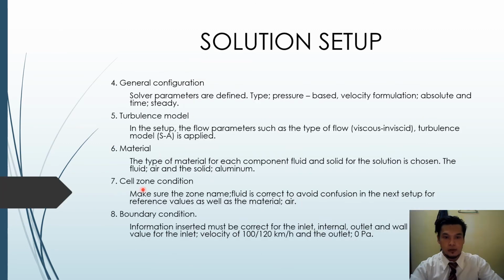For the cell zone condition setup, make sure the zone name is correct, which is the fluid, and the material also is correct, which is air, to avoid confusion in the next setup for reference value.